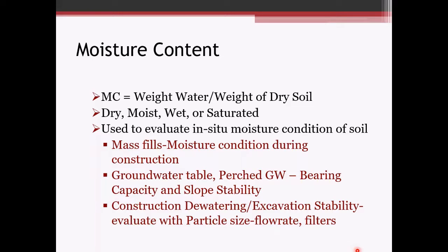As you get to the wet side, that's going to be wet of optimum, and the material is going to typically become a little bit unstable once it gets on the wet side. And the material that's totally saturated is typically going to be below the groundwater table, where 100% of the void spaces are filled with water.